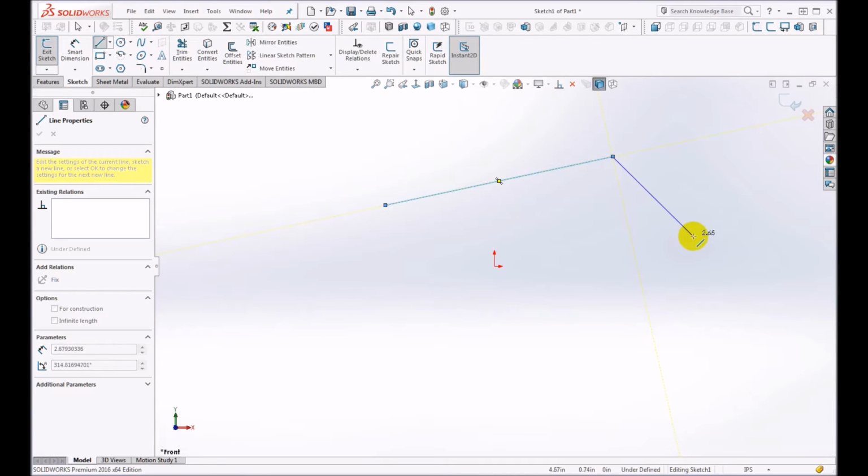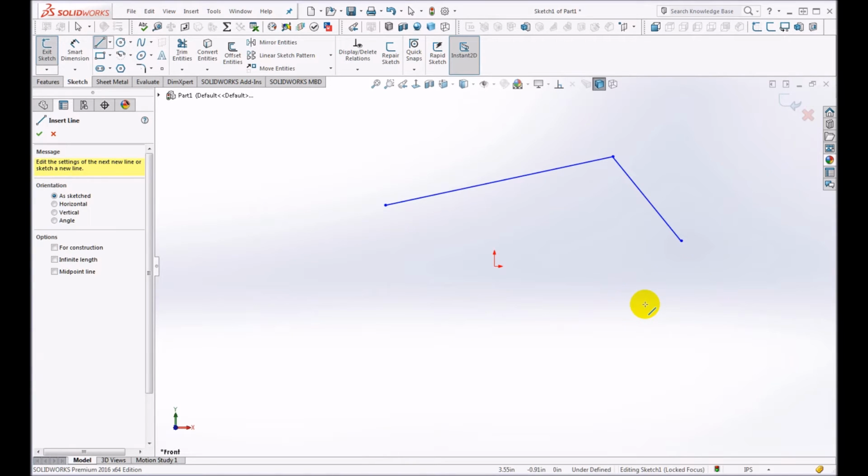Right now I'm going to click not on one of those lines, click again, and if I decide that I'm done, what I can do is either press the escape key to leave the line tool altogether, or double click, which is what I'm going to do, and that ends the current line, but it keeps me in the mode of drawing another line. So you notice that the cursor still has that line appearance.